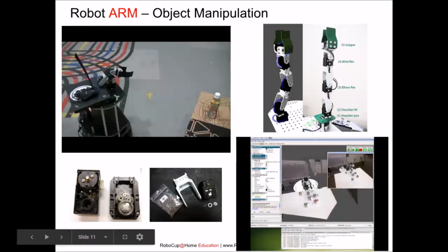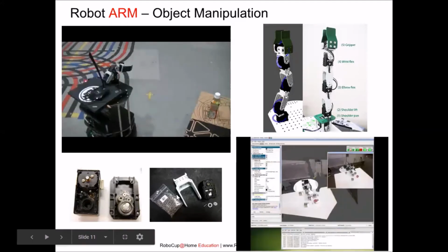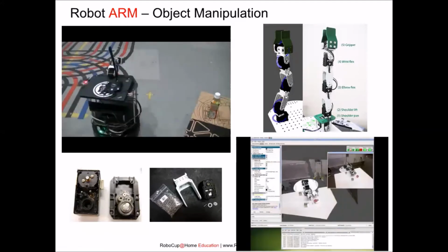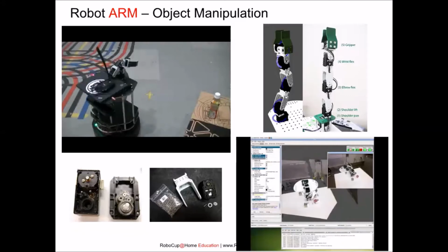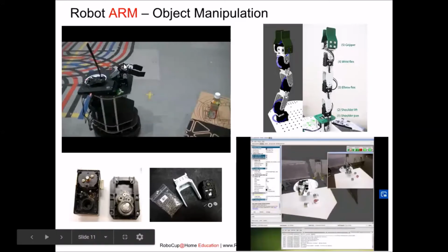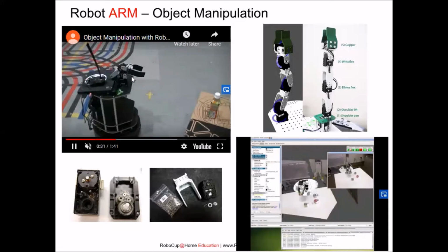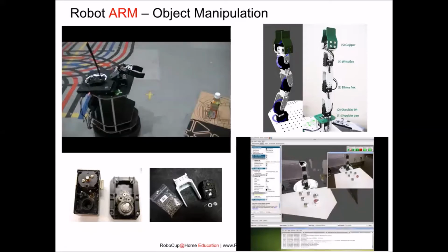It controls the turning angle, which then rotates the joint, right? With the joints and links, we build up something like this, which is what we call the TurtleBot arm, and then we mount this arm on the robot, and it works together with the base. So this system actually extended from the conventional industrial arm application into something we call mobile manipulation.